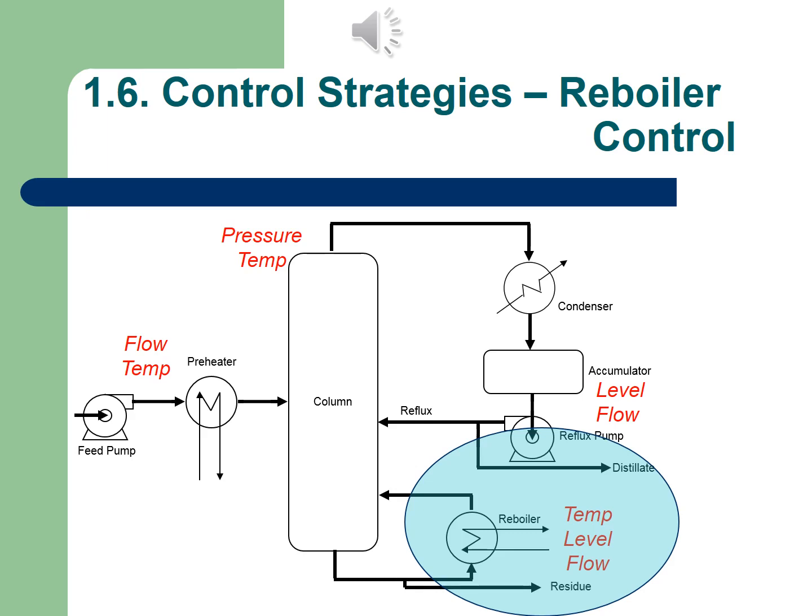Okay, on the next section, so we are done now with the pressure control. There's a few strategies there that could be implemented. Then also we had looked at the feed control, where you had your flow and your temperature control in a cascade manner. So now we're just going to look at the bottom products control. That is basically your reboiler, and that's adding the main heat to your distillation column.